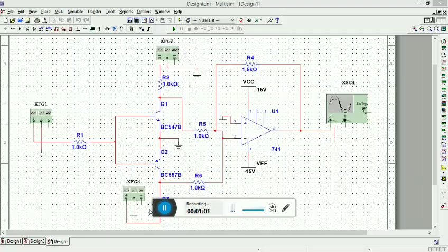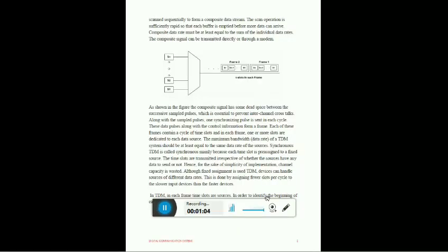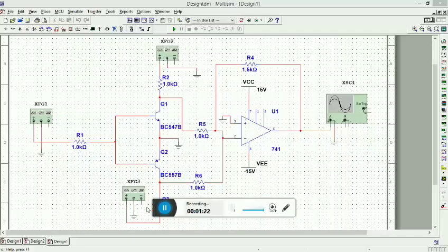So what is TDM? It is a method of transmitting and receiving independent signals over a common signal path by means of synchronized switches at each end of the transmission line so that each signal appears on the line only a fraction of time in an alternating pattern. It is generally used when the bitrate of the transmission medium exceeds that of the signal to be transmitted. In short, we can think of TDM as a multiplexer which switches between its inputs and selects a particular input to be transmitted as the output over the carrier signal.